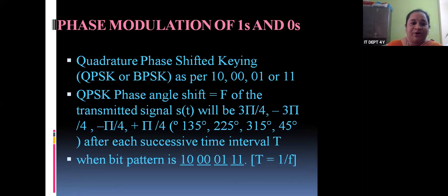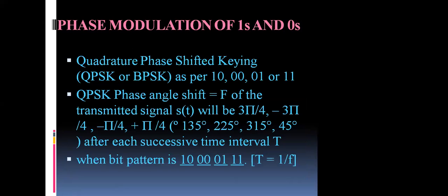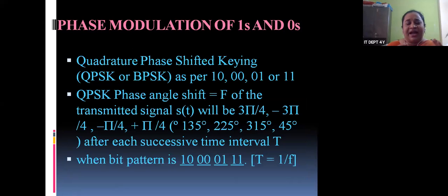And this particular phase modulation can also be represented with 2 values or 4 values. If you have only the 2 digits, 1 and 0, then it is called binary phase shift keying. But if you are going to have multiple combinations, that is, multiple amplitude levels of the modulating signal has to be represented, other degrees can also be shown by having the combinations 1 0, 0 0, 0 1 and 1 1.